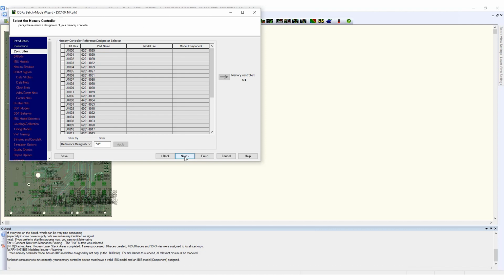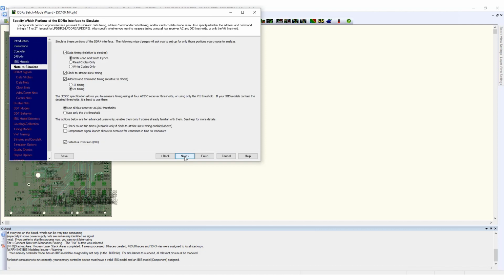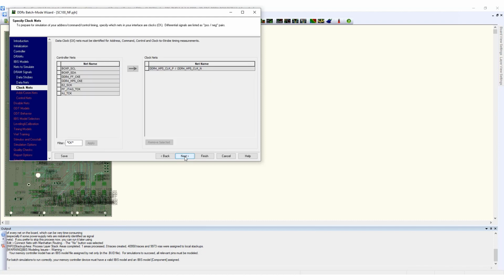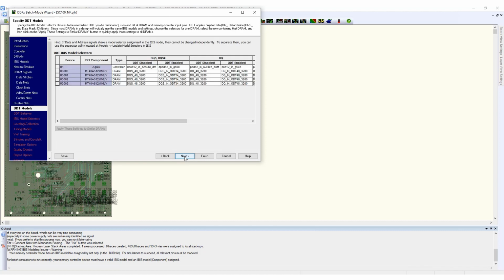The DDRX wizard helps us to configure a complete DDR4 test bench. All requirements from timing margin to signal integrity characteristics are considered. With the different ODT settings, HyperLynx is capable to simulate the read and write use case.